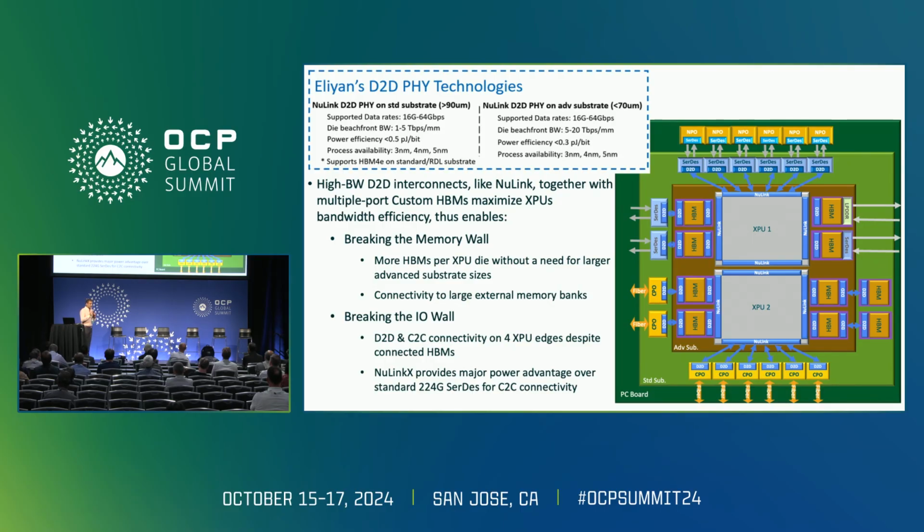But the other key advantage, something we've been promoting in the industry since 4 years ago, is using a FinFET base die for these HBM, so we can do more things. And one of the key things we can do with it is building a multi-port HBM. And once you do that, you can do a lot of interesting things, as you can see.